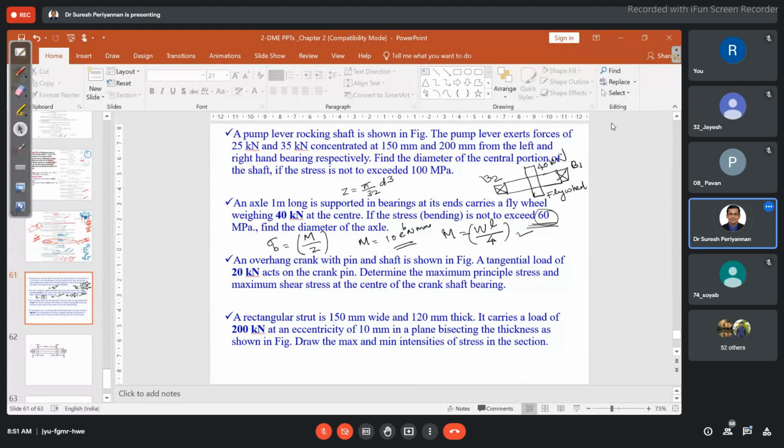Yeah, thank you. Now, the second case: verify that the deflection of the shaft should not be exceeded. We have found the diameter of the shaft. Fine. Now, another restriction we have not yet considered, right? While transmitting the power, the whole arrangement should not deflect beyond 0.36 mm. Based on that, we have to verify our shaft diameter.